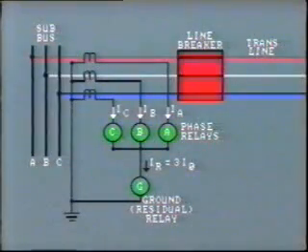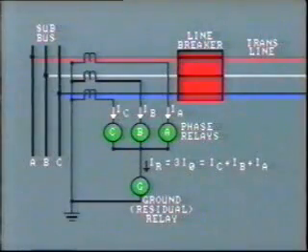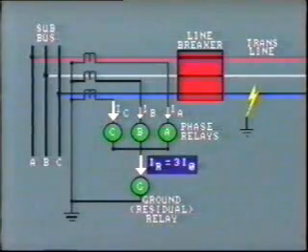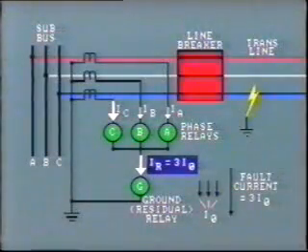As you know, the residual current, IR, is the phasor sum of the three-phase currents. Normally, it is very close to zero, but when a line-to-ground fault occurs, this current becomes very large. You will often see the residual current expressed as 3I0. Remember, the magnitude of current for a single line-to-ground fault is just 3 times its zero-sequence component.